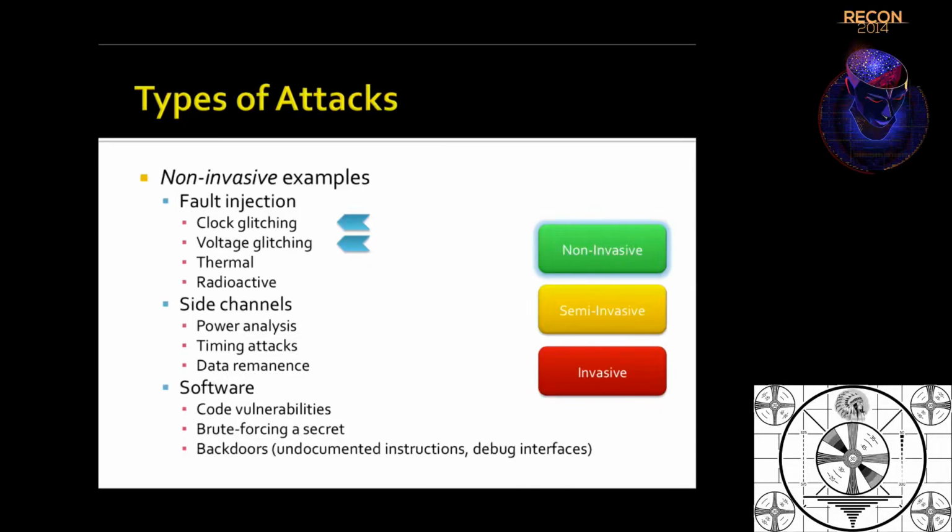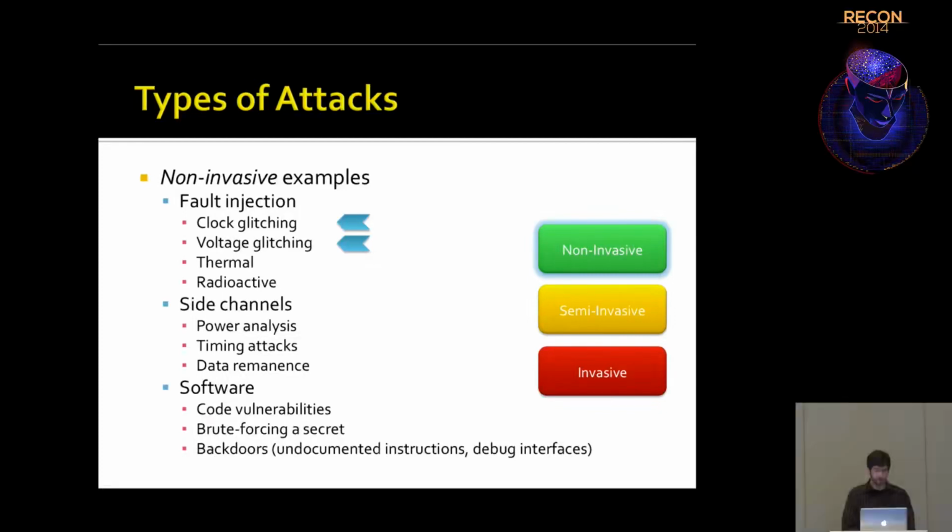The second subfamily of non-invasive is side channel. There's power analysis, which is basically analyzing the current or power consumed by the device in response to what stage of execution or operations the chip is doing. And actually Colin O'Flynn is going to be giving a really good treatment of that on Sunday, so that talk is something to look forward to.